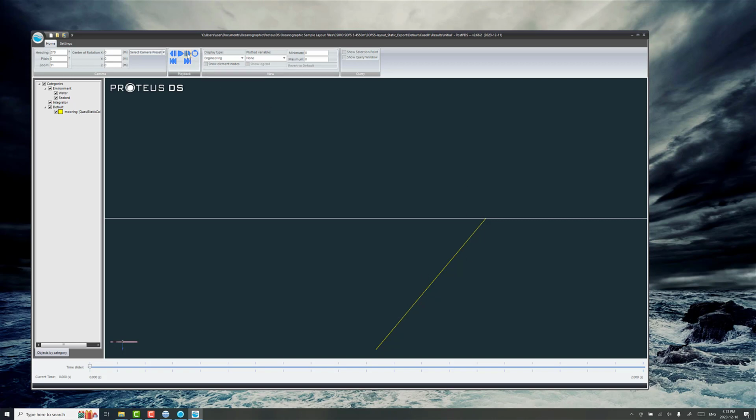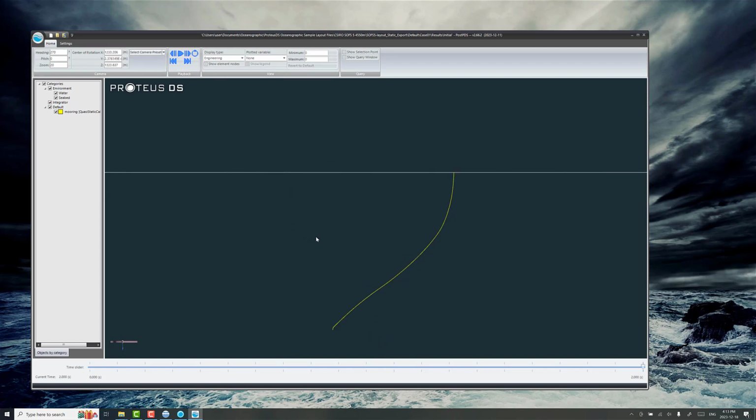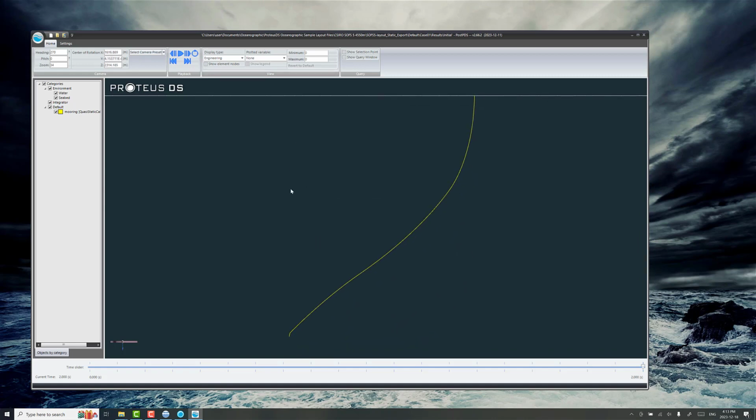So the first calculation is the estimated mooring position in zero current. So there's a positively buoyant section. The wire rope will come down here, negative fiber rope, and that's roughly how it's going to sit in the water column when there's no current. And here's the profile of the mooring when we've got that particular design current that we're working with.